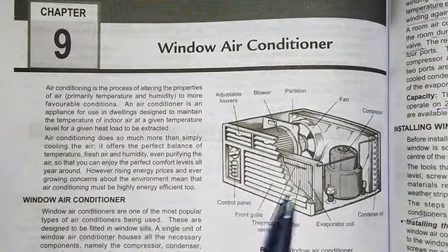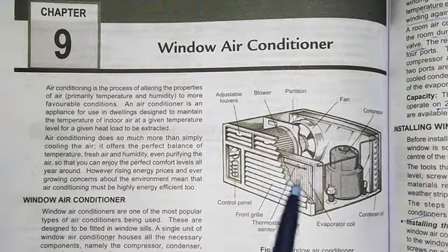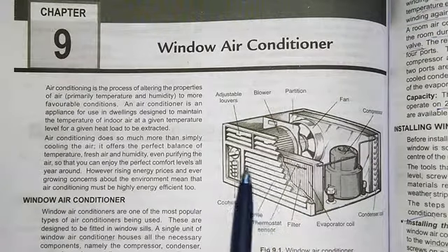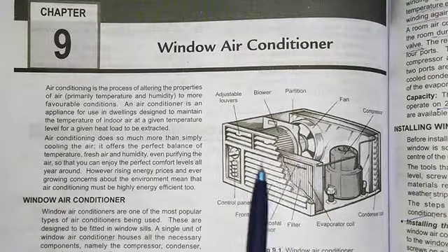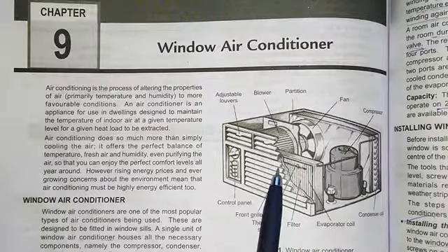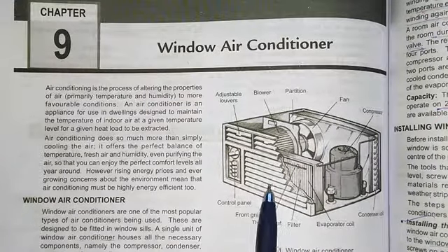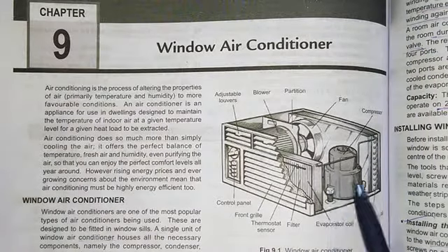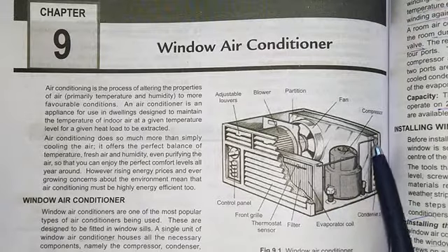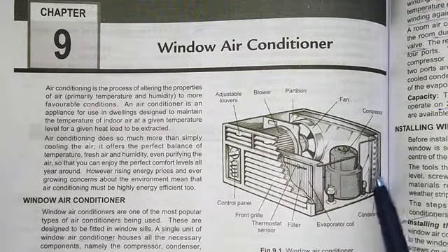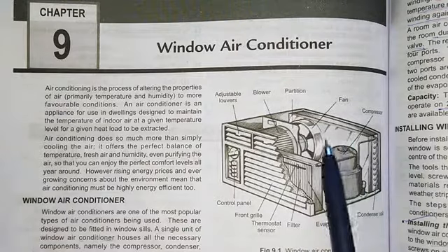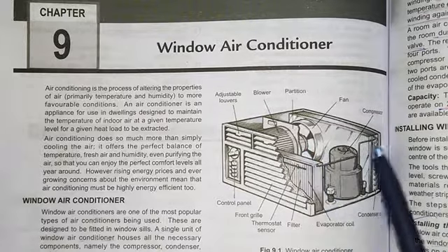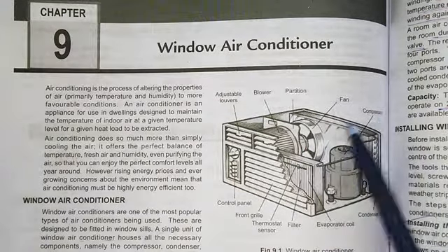So see, the refrigerant is here inside this evaporator coil, and this front panel is inside the room. So it extracts heat from the room and gets vaporized. The vaporized refrigerant then goes to the compressor, where the compressor raises its pressure, and then this refrigerant passes through this condenser. These are the condenser tubings, and it cools by the action of this fan, by forced convection. So this is the rear portion.